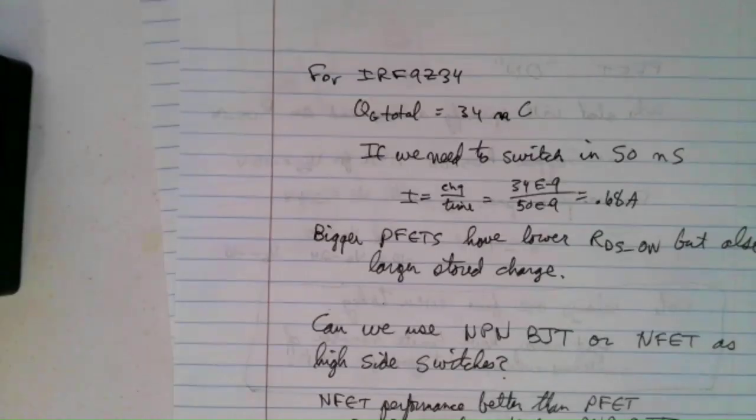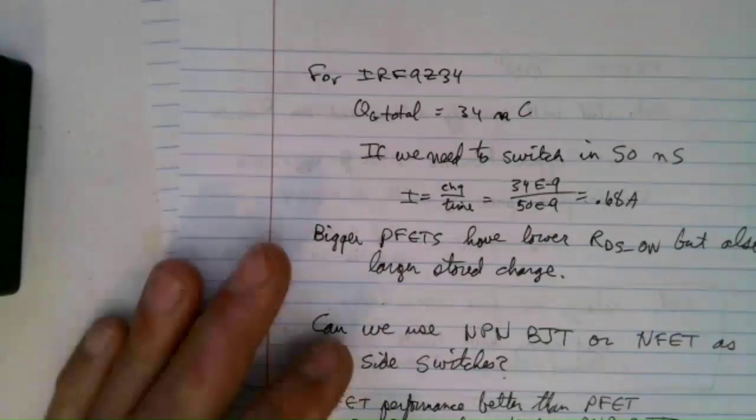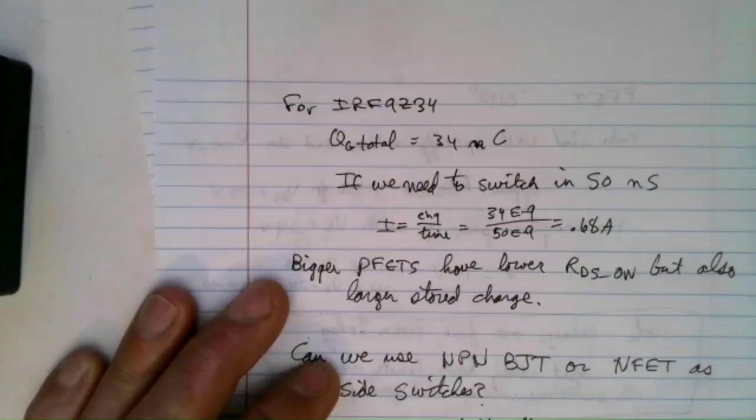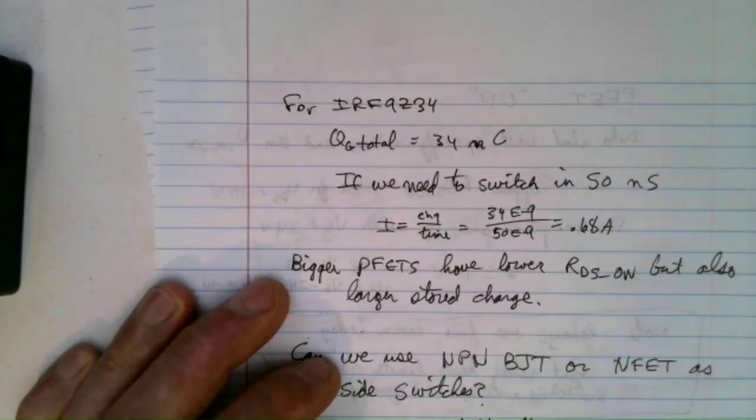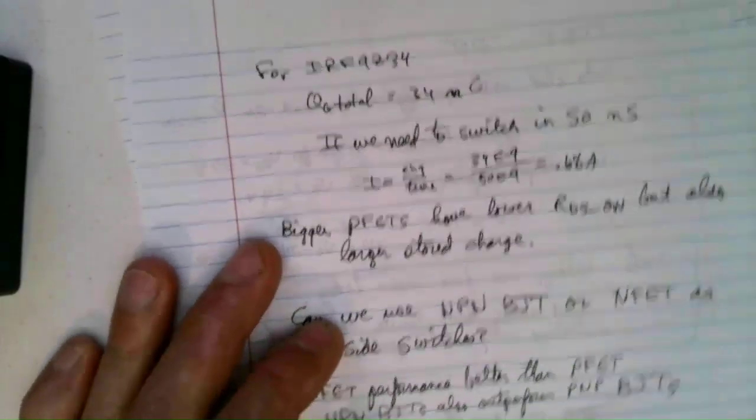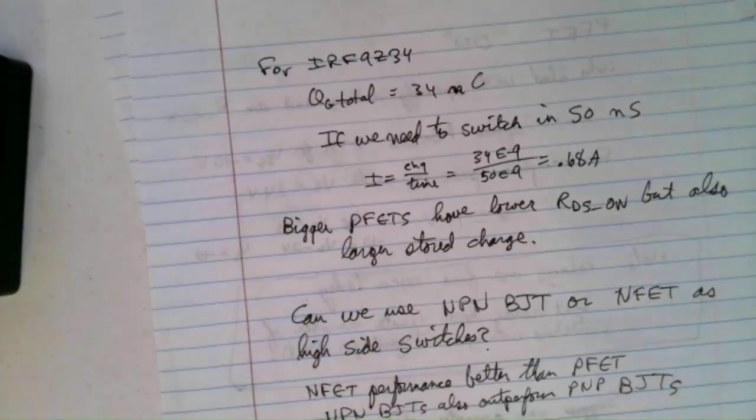And so it's going to sit there and want 150 amps instead of 15 amps, and it'll vaporize your electronics unless you've been careful. So you probably need a bigger FET with lower RDS on, and then some kind of a current protection so that you don't vaporize stuff if the motor can't run because the shaft is locked, let's say.